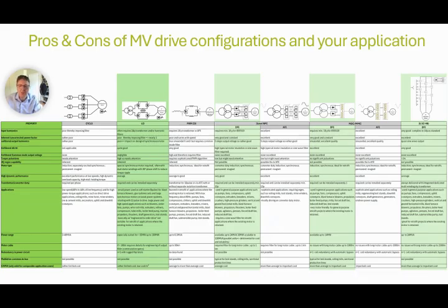The converter duty transformer can be integrated or installed independently from the drive. The cycloconverter requires one per phase, and all other topologies except for the PWM CSI with active front end require a multi-winding transformer realizing a minimum of a 12 pulse in-feed. The 2-level series Cascaded H-bridge is always delivered with an integrated dedicated multi-winding dry transformer.